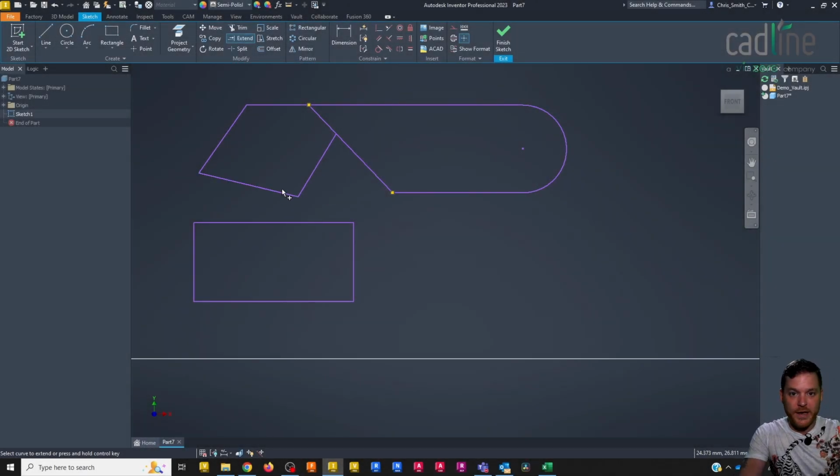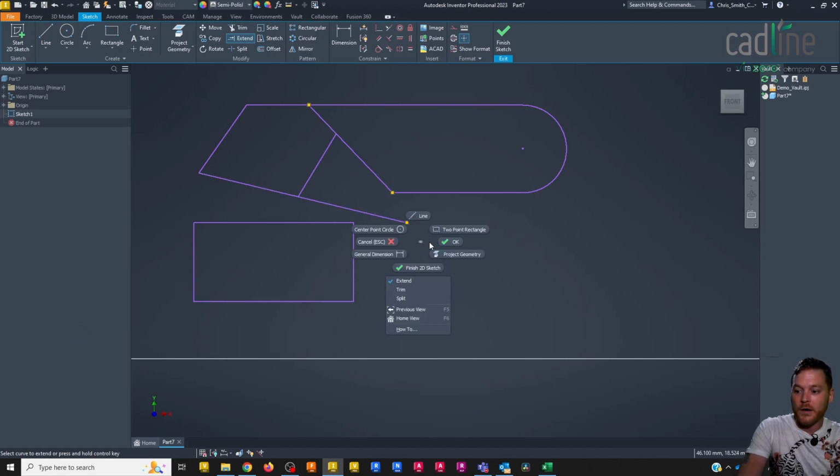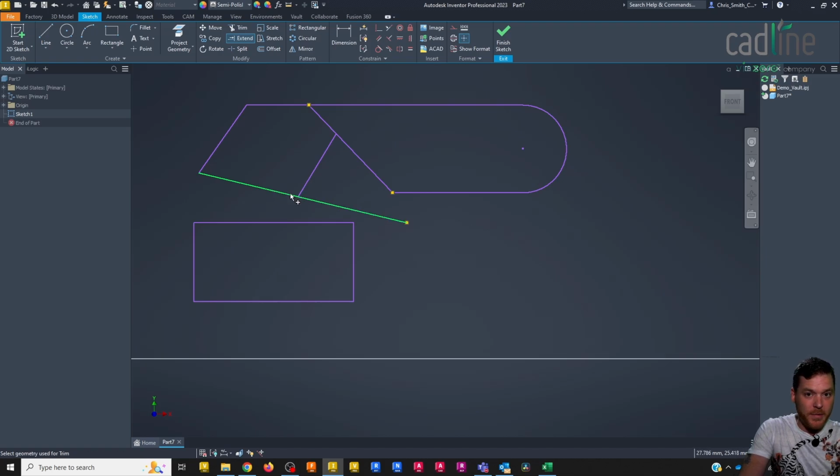Something else that we have is a deferred point in this tool. So the extend and trim tool, you can see it's actually extending to a theoretical point. So where these two lines would touch, it gave me that point. We can also see it's going to where these lines would intersect. So again, I will select that. I'm going to right click and change to trim, and we see it will trim up to this line, up to this point. If I hold Control, we notice that it won't let me trim anything because I'm getting rid of that deferred point.